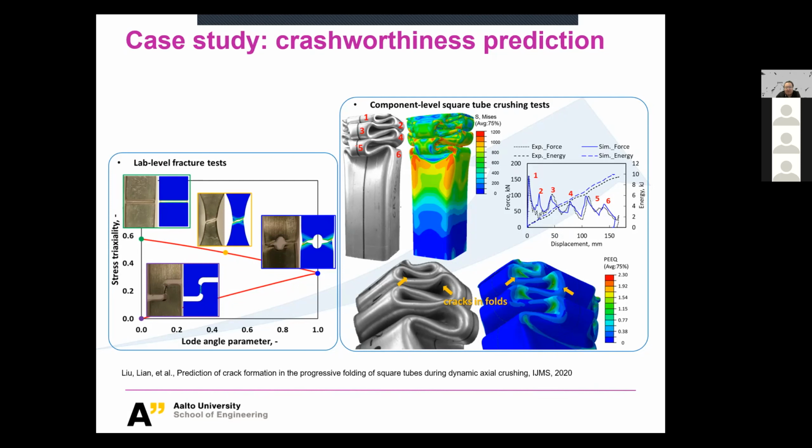So this is the so-called crash box. This is a part of the crash system in a car. Every car has this, and usually you have two of them. They're put there to absorb energy when you have a crash, so the passengers inside the cabin could be protected. The way for this kind of structure to absorb energy is to generate this kind of folds. Initially it is a completely straight column. You will see a nice video over there.